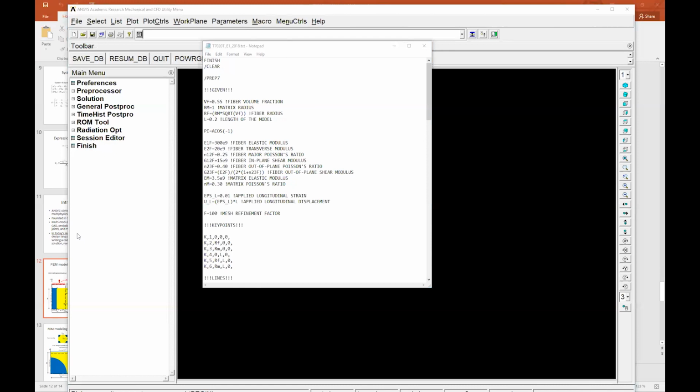On the other hand, how is Workbench working? You create the geometry, you apply the boundary conditions, and then Workbench assembles all this information. As you press the solve button in Workbench, it converts the problem to the APDL language. So it is sent to APDL where the solution is done, and all the results are then collected and exported back to Workbench. So as a solution engine, it's still using ANSYS APDL.